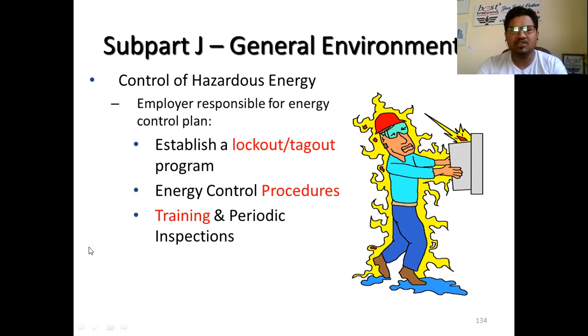It can be any toxic gases, it can be any hydraulic or pneumatic energy or spring loaded, so any energy, even electrical or mechanical. So any energy which can create or could be harmful for our employees, we need to lock out and tag out before we start a project.